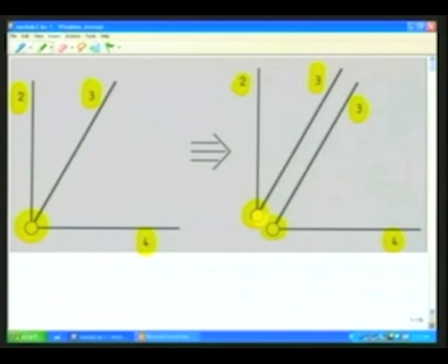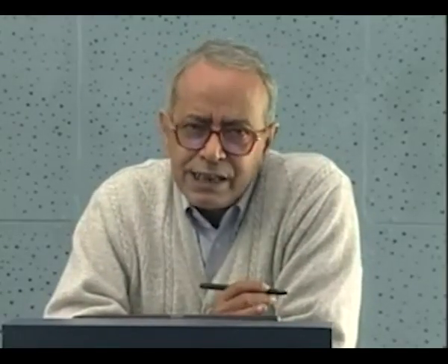This way, I can think of another type of hinge where 4 links are connected. And such a hinge will obviously be equivalent to 3 simple hinges. Maintaining this equivalence between higher order hinges and simple hinges, we would like to modify the equation for calculating the degrees of freedom of a mechanism as follows. When higher order hinges are present, the symbol j in the equation I would like to modify as follows.